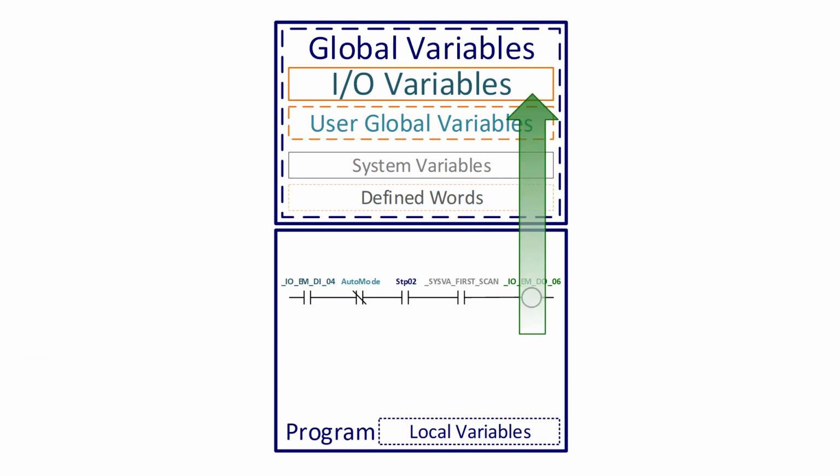The last instruction, the fifth instruction, a direct coil, writes to the memory location that it is addressing. If the rung collectively is true, then it writes a 1, or rather turns that bit on in memory. Consequently, if the rung state, the overall state, is false, then it writes a 0 to that memory location or turns it off. Now, we started with an input variable and concluded with an output variable. We started by reading something from the I/O variables, and then we concluded by writing something to the I/O variable. That wasn't really on purpose.